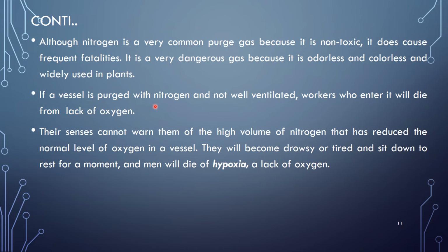If a vessel is purged with nitrogen and not well ventilated, meaning there is no sufficient air circulation inside the vessel, the workers who enter will die from lack of oxygen. Already I told you, the person facing lack of oxygen has a problem, that is hypoxia. Don't forget.